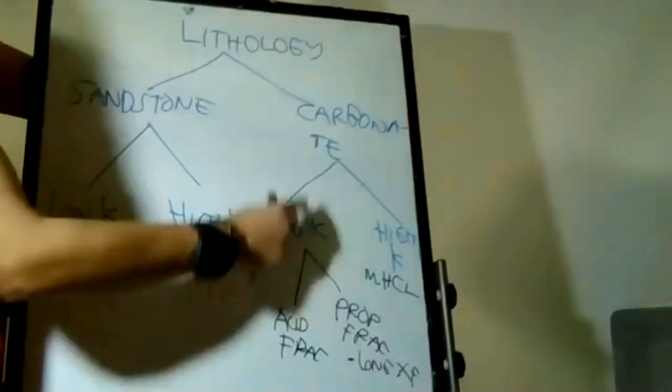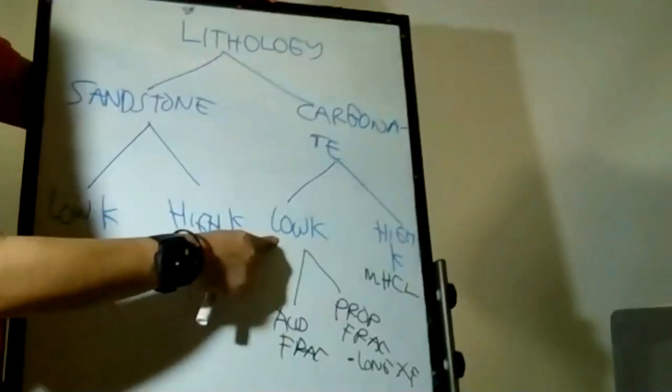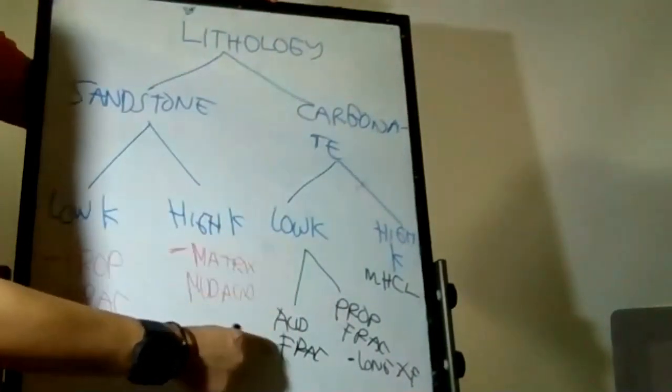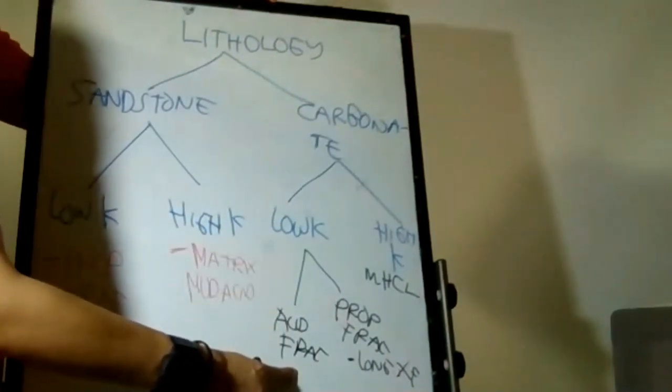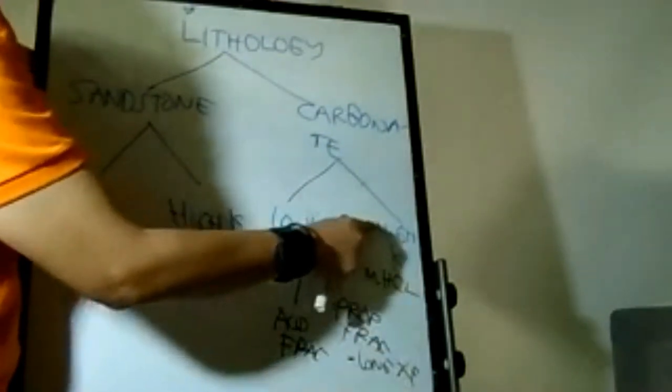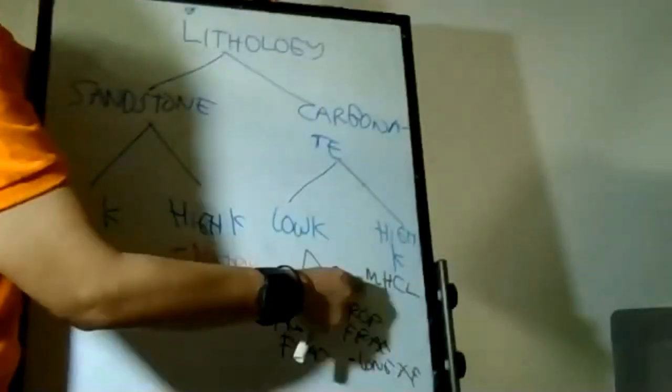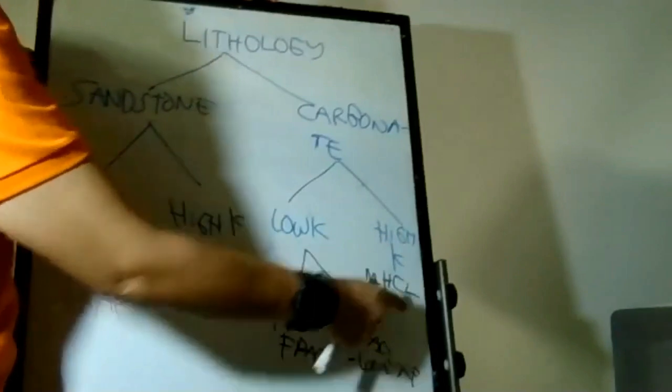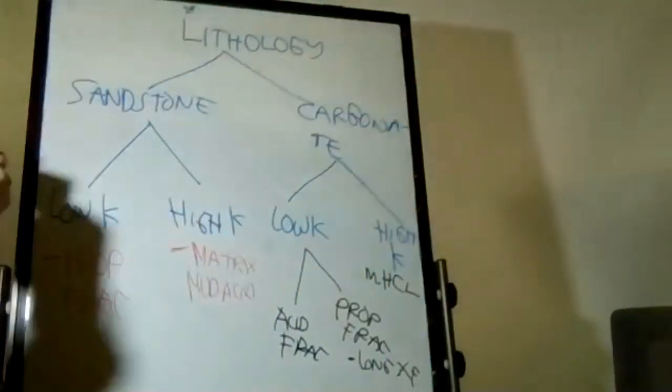When you deal with the carbonate reservoir, low permeability, you have two options, acid fracturing when the solubility is good, or proppant fracturing with a long half length, right? Now, with the high permeability, then you can do matrix acidizing. Let me add something here.